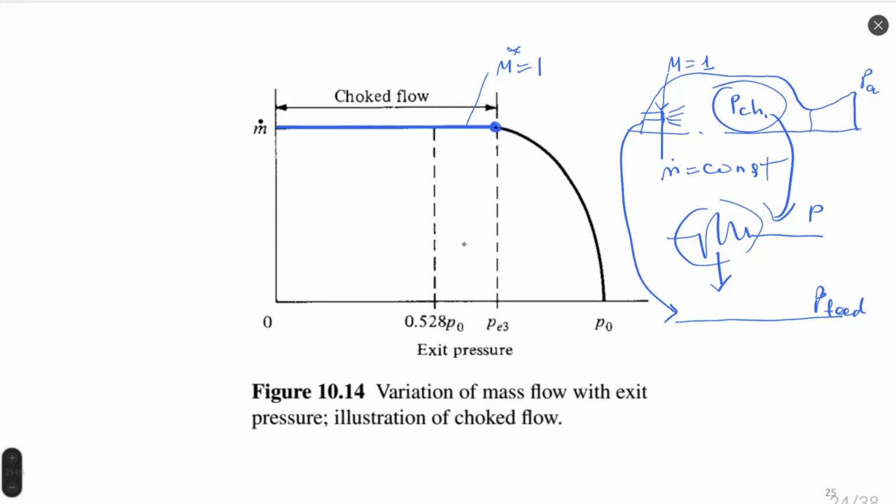Flow structure inside the nozzle will change for different altitudes, and the external flow can also change. But since chamber pressure is more than 2 times higher than ambient pressure during motor operation, this ambient pressure will never influence flow conditions and flow structure inside the combustion chamber processes.